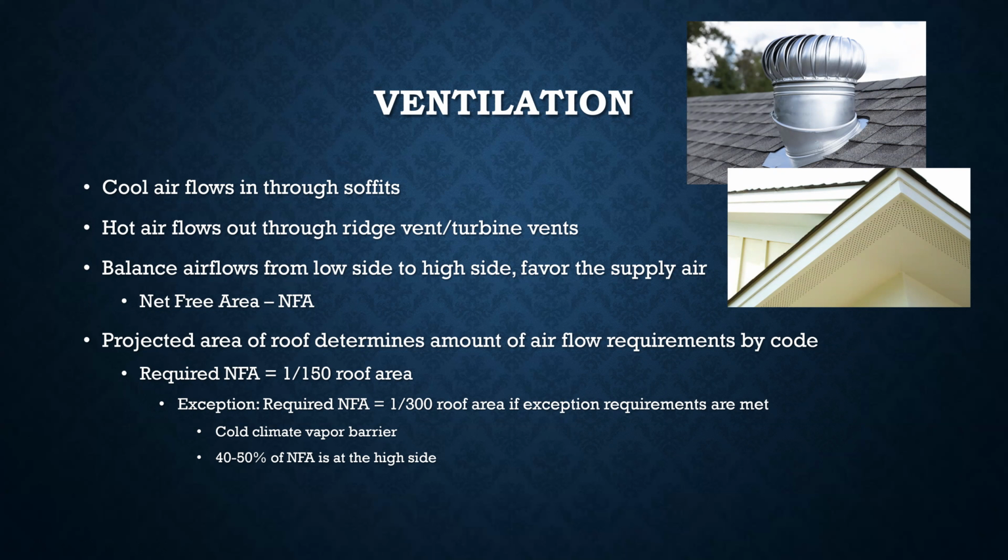An extremely hot attic would also be a problem for the inside of the house, because if you have insulation in your ceiling and it's not very good, you're going to lose a lot of heat, and you're going to gain a lot of heat in your house. Either way, it's bad. So you want a well ventilated attic in most situations. If you don't have an attic, there are other ways to deal with that, but we're not going to talk about that at this time.